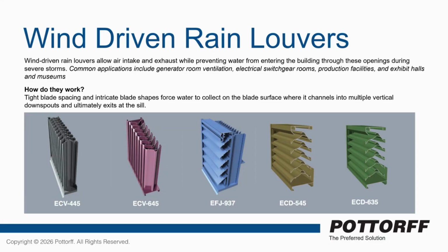But your biggest concern here really is preventing water from getting into the building, and particularly into some type of room that is going to have specialized equipment, or very sensitive equipment. What you can see on there are some examples like a generator room or an electrical switchgear room, something that's going to be very necessary for the building to keep performing. Or you could potentially have something that does have people in it as well. But the tight blade spacing on these really does prevent a lot of water intrusion.